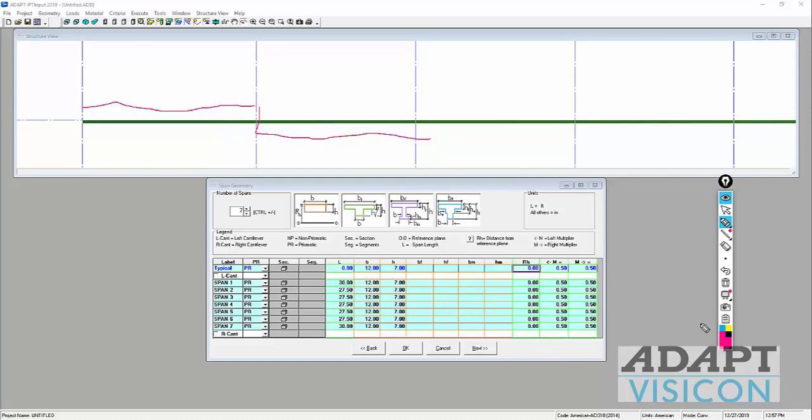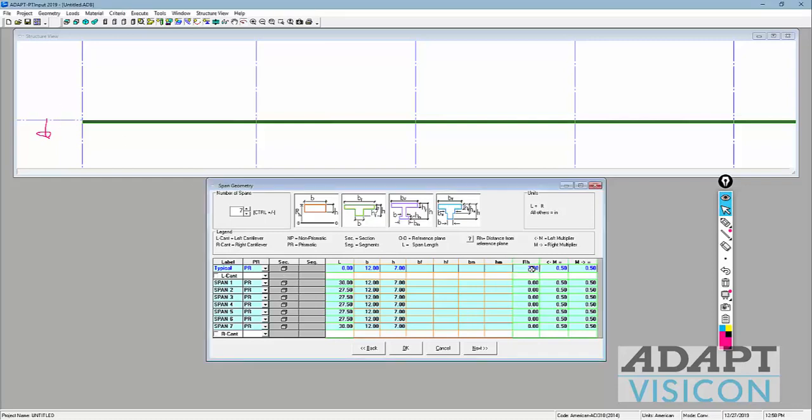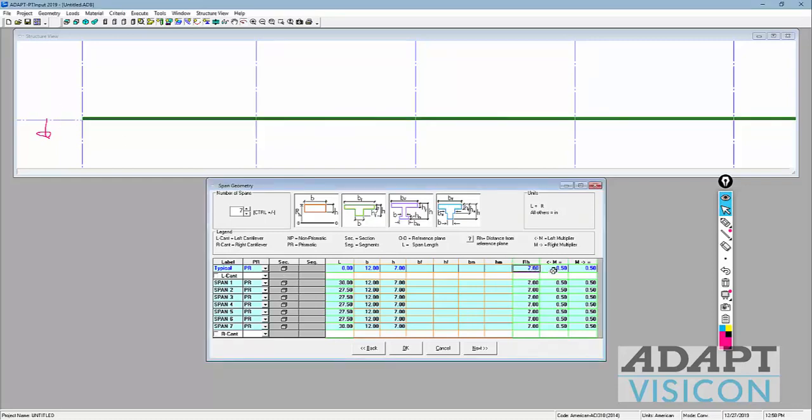However, if we leave this slab, which is the same elevation along each span, at 0, the control points for the tendons are going to be based from this datum downward, so they'll all be negative, which is not typically how we reference them on plans for construction drawings. So I'll set this equal to 7 so that the program will represent everything upward, which will be positive from the slab soffit. So we'll go ahead and press 7, enter.